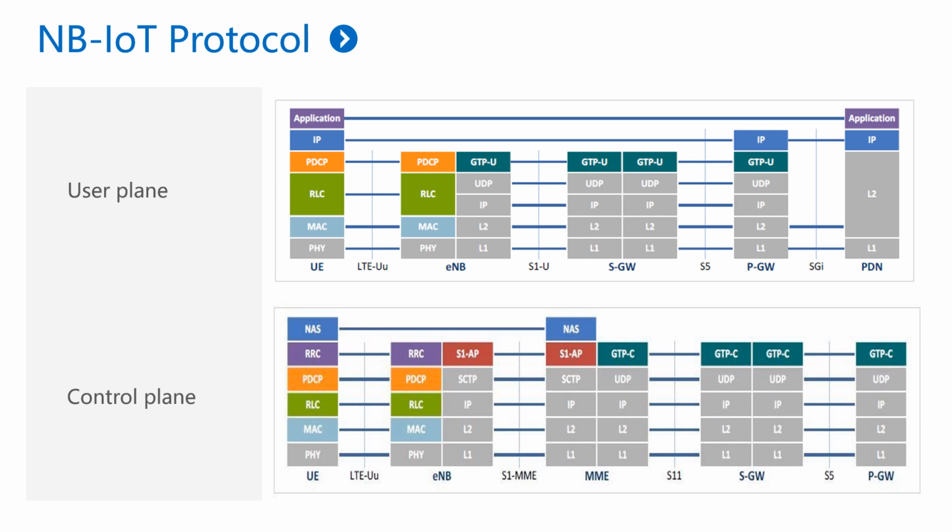In both planes, the radio link control (RLC) layer is responsible for grouping and concatenation of RLC service data units (SDUs) to meet the requirements of data transmission, and for the reorganization and decomposition of the RLC protocol data units (PDUs) received by peers. In addition, the sliding window method is used in RLC to sort data packets, and the automatic repeat request (ARQ) retransmission of data packets is realized through RLC status reports.